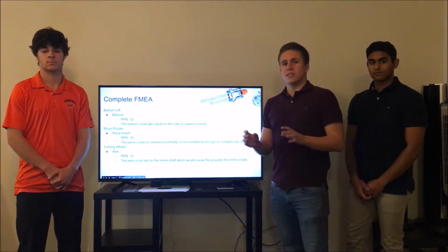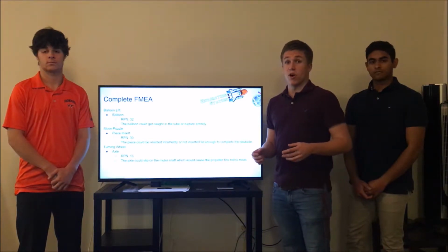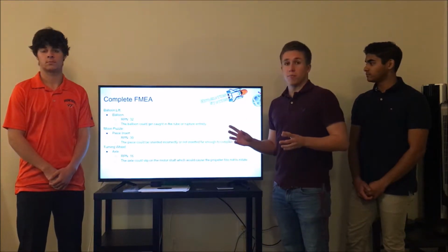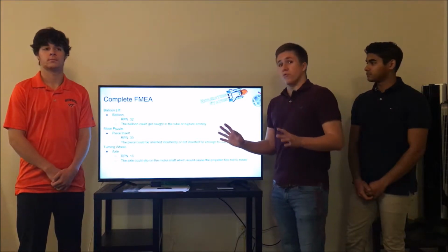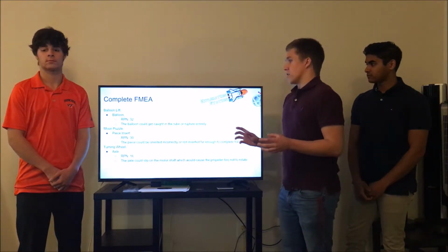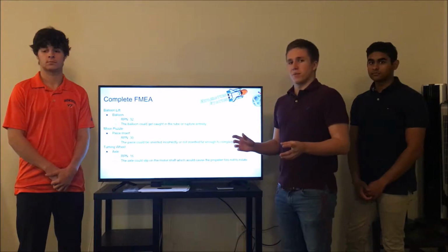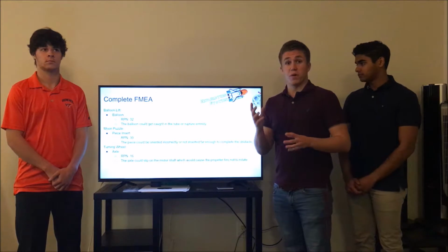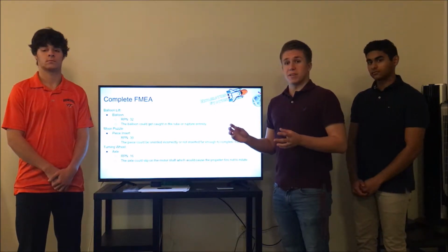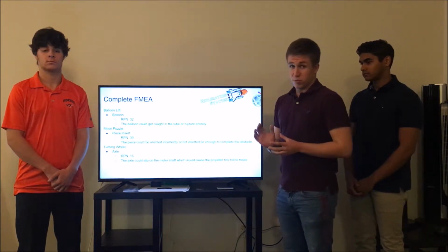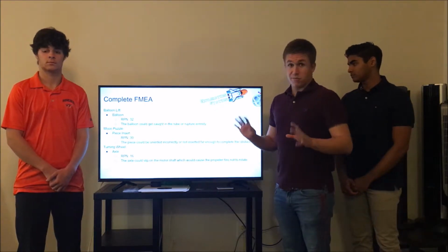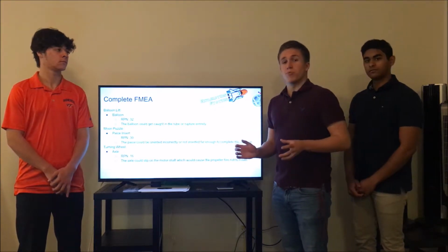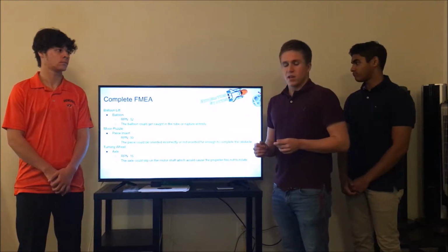Alright, first of all, we did a complete failure modes and effects analysis on the BRG. And right here we're going to cover just one mode of failure for each obstacle. So for the balloon rocket lift, a mode of failure was the balloon. We found that there were times that it would just pop, and most of that was due to it getting caught with the pin at the very top, or maybe getting stuck on the inside of the tube. The RPN for this failure mode was 32, so kind of right in the middle there. Not super important, but still something we wanted to fix.